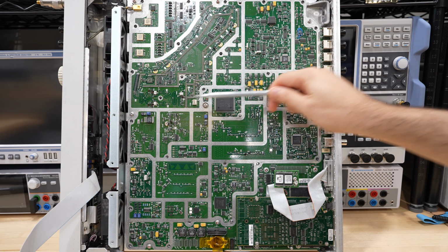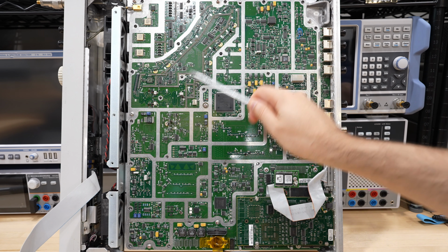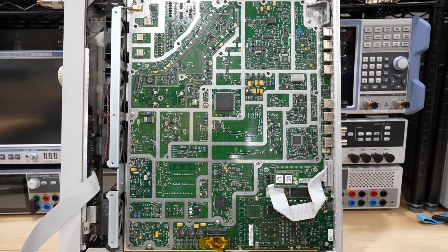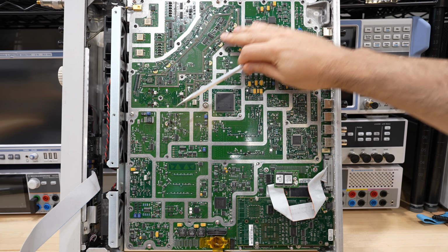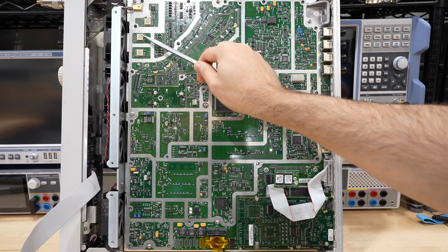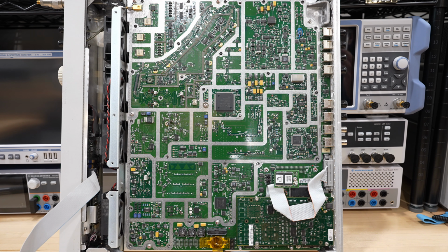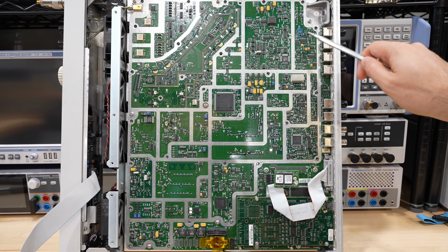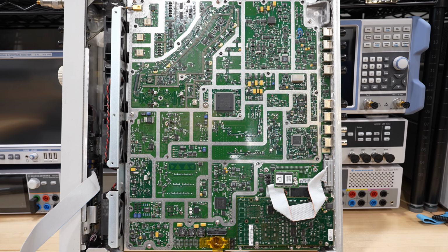Over here is the entire output section. You can actually see the individual paths for the low band, high band, and the heterodyne band, all of them converging ultimately into one path and going through 3 custom ICs at the very end, reaching the output, most likely the power amplifiers, and possibly maybe some of the final mixing stages and ALC and all that in that area. Again, that section is working, so we don't have to really worry too much about that. There's some crazy budge over here as well. There's some digital stuff in this corner. Again, nothing to worry about.